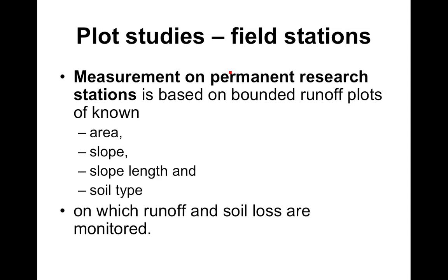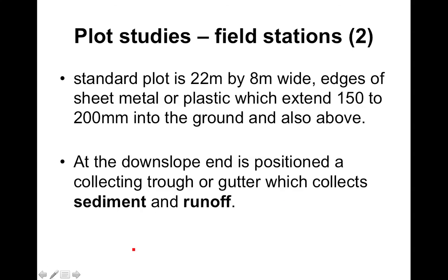So you can use plot studies at field sites, right? So you can set up a permanent research station at a site and one advantage of that is you can bound off an area so that you know the area over which something's happening, and you can know the slope, and potentially the length of overland flow, and you can characterize the soil type, and then you can measure runoff and you can measure soil loss, right? And you can set up standardized plots as well, right?